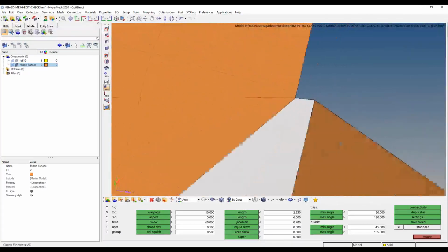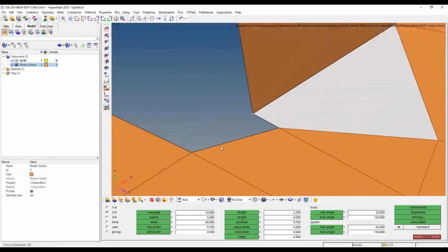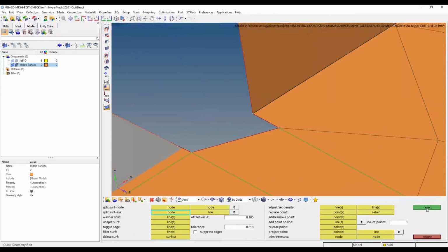Instead, I just got a few other ones. So likewise, I got those keyhole slots giving me problems again. So like we had done before, where I'd gone into my F11 quick edit menu, you're going to learn a little trick here. F10, F11, and F12 are all next to one another. You're going to be bouncing between those all the time. F10, F11, and F12 are like the three musketeers of surface meshing.